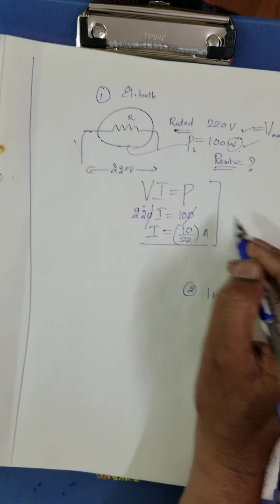Now what is parallel combination? Reciprocal of effective resistance in the parallel combination is equal to the sum of the reciprocals of the individual resistances, and so on. Here 1 by x plus 1 by x plus 1 by x, 5 times, right? I'll write it. Therefore 1 by Rp equal to 5 times 1 by x or 5 by x. If you reverse this, Rp is equal to x by 5.